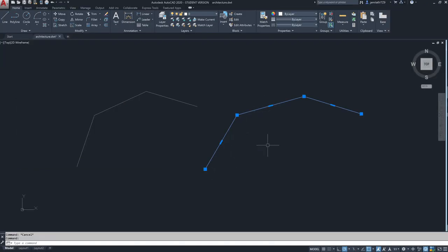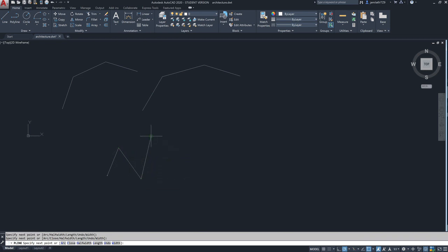So what is the difference? The line command creates line objects separately. Every time you create a line, with a starting point and an ending point, that would be one standalone object. But a polyline is going to be one object until you finish the command. So I'm going to select the polyline command, draw a polyline like so, and press spacebar. Now if I select here, it will select the whole polyline. It's like one object. Isn't that the difference between line and polyline?